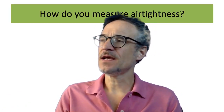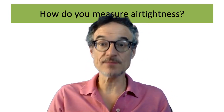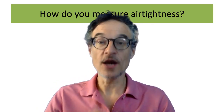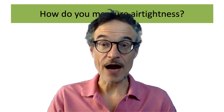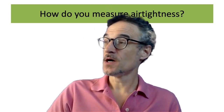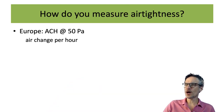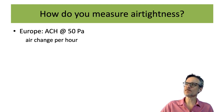Air tightness is measured. How do you measure air tightness? We can measure most things if we try, and if we want to make a low energy building, we need to measure so we can find out how much energy we're actually using. And we can measure air tightness. In Europe, the measurement is usually air changes per hour at 50 pascals. I'll talk about that in a moment.